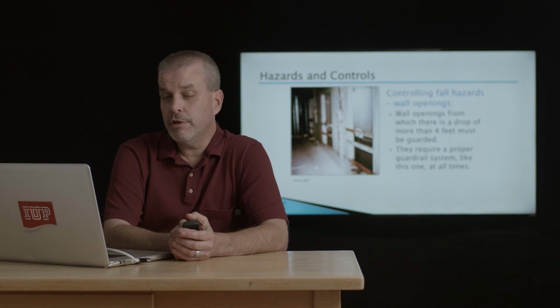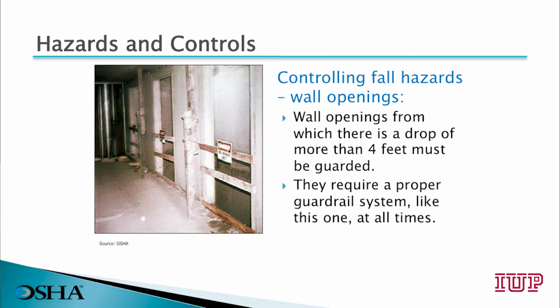Controlling fall hazards associated with wall openings. As you can see in this photograph, wall openings from which there is a drop of more than 4 feet must be guarded. Wall openings require a proper guardrail system, such as this one, at all times.